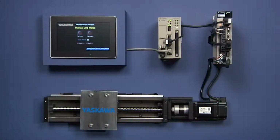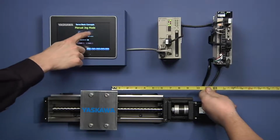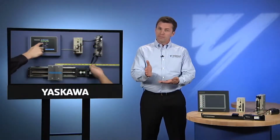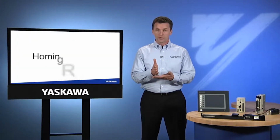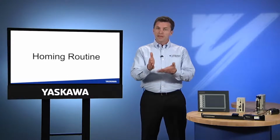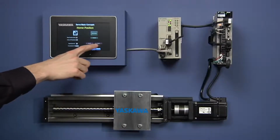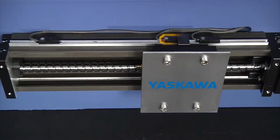A very simple way to accomplish homing is for the operator to visually align the axis to its 0 position. In actual practice, however, most machines rely on a fully automated sequence called a homing routine. Here is a typical homing routine in a controller. The axis first moves slowly in reverse, then stops when it detects a dedicated sensor known as the home sensor.